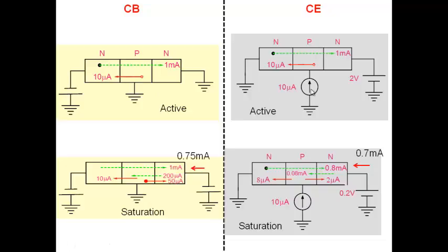Okay? Very often, in fact in most of the textbooks that you'll find, this is an error that you'll find almost everywhere, where people think that the current is falling here in common emitter mode because of a similar process. The current is falling in common emitter mode because of a different process here.